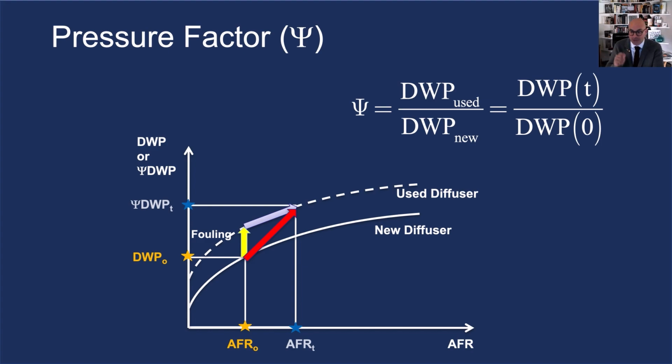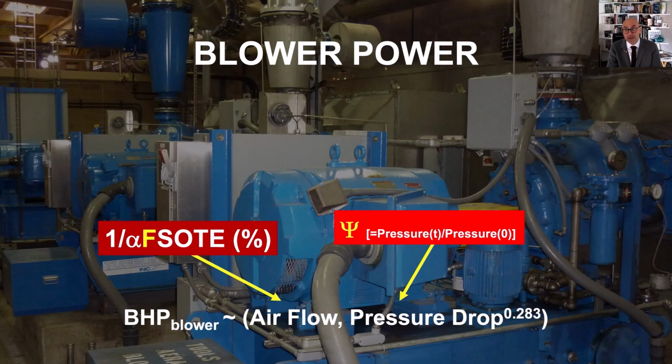If you don't have enough efficiency or you don't have enough air, the plant will just not have enough oxygen. But if you don't have enough pressure, the plant will not have any bubbles. Bubbles will just simply not come out. So it's very important to consider that this is a logical indicator, either or. You either have enough pressure or you don't, okay? Whereas the airflow rate is a proportional indicator. Let's go back to the blower house and look back at the proportionality.